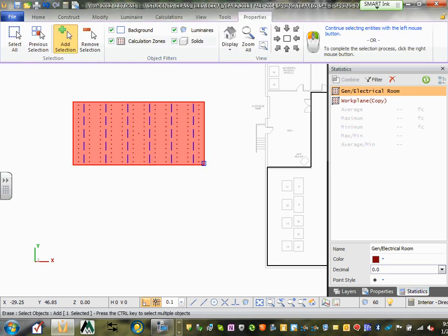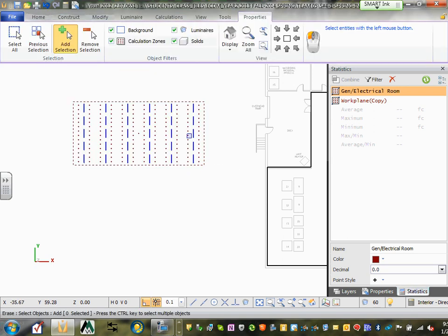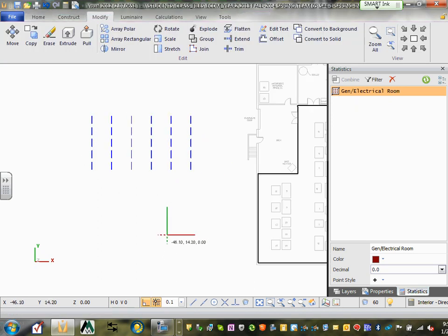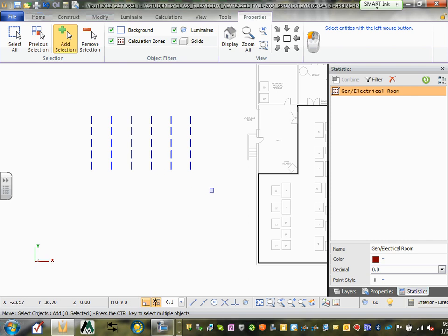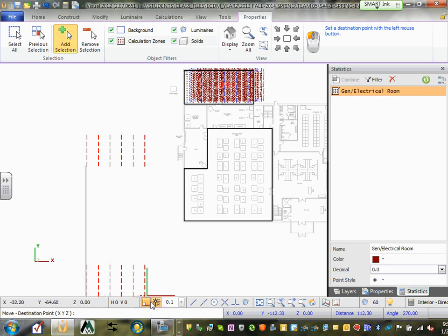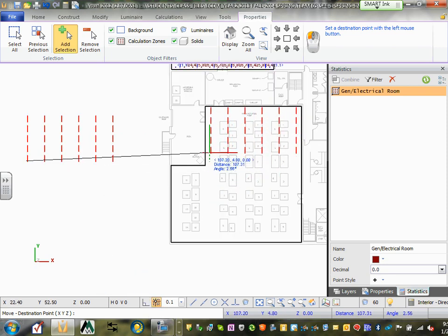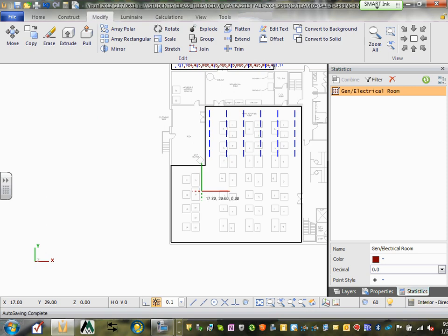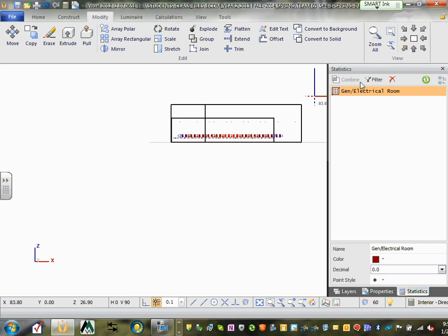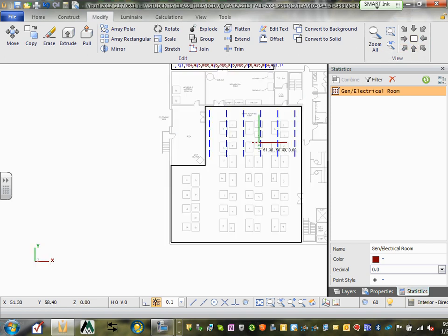Absolutely. You can also click on this one, guys. Delete it right now. Can you guys see I'm deleting all the calculation? The only thing left here is the lighting fixture. Now you come over here, grab your lighting fixture, right click and drag it. I'm dragging it. If I want to get off the ortho, I can drag my lighting fixture and place it approximately in this location. And if you look at 3D, here's my fixtures located at this location. Then you can drop the second, the third and the fourth.